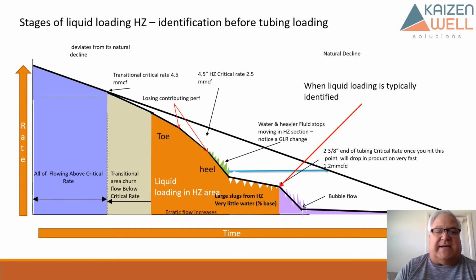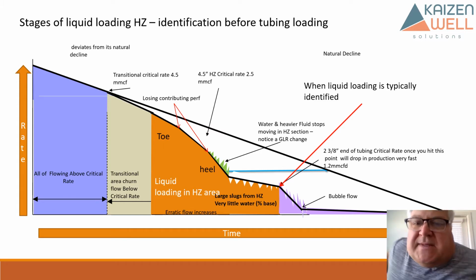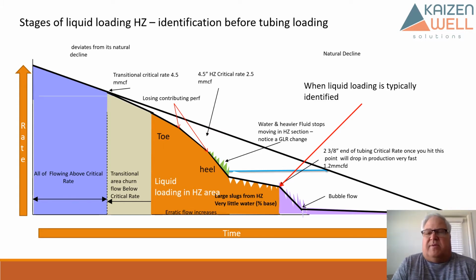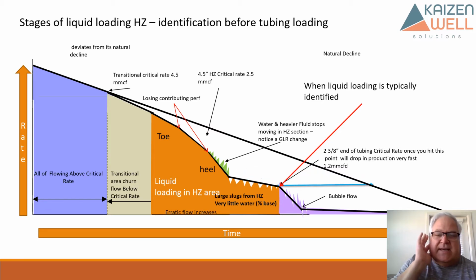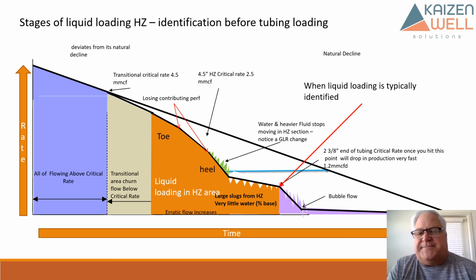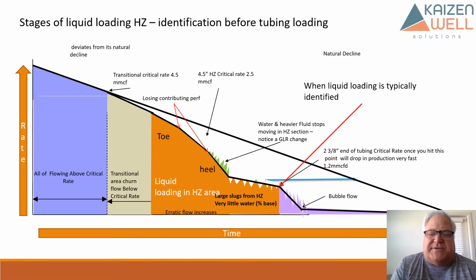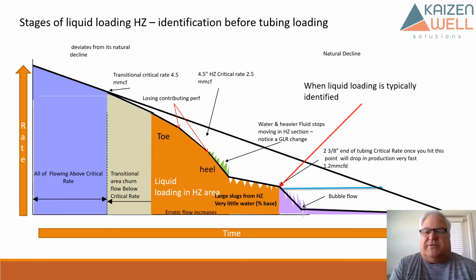A lot of wells that we look at are actually liquid loading very shortly after they're brought online. But what we're always trained to look for is liquid loading in the tubing. Now, the problem with that is this well has been liquid loading all through the toe, through the heel, transitional area for a long period of time, and long before you get to liquid loading in the tubing. So we come along and say, oh, we're at critical rate now in our tubing, forgetting that we've been liquid loaded behind the tubing, and we start doing something. We'll put a plunger lift in, or some sort of deliquification method.